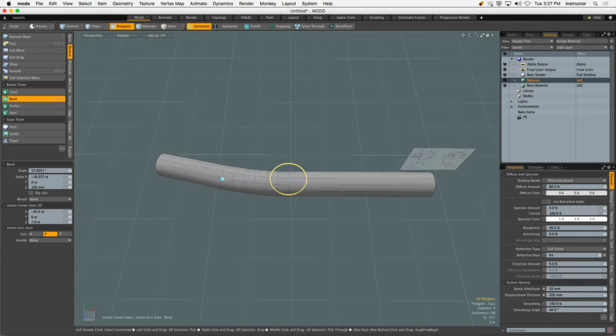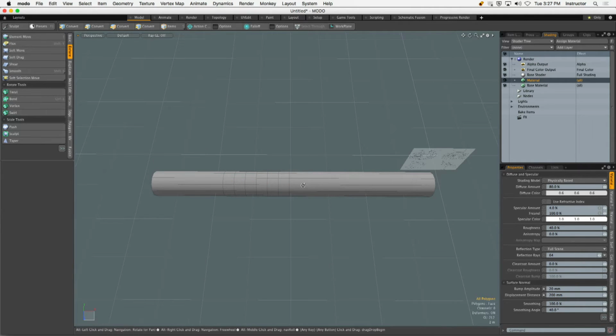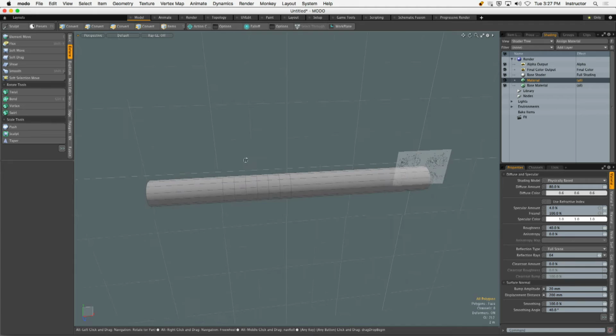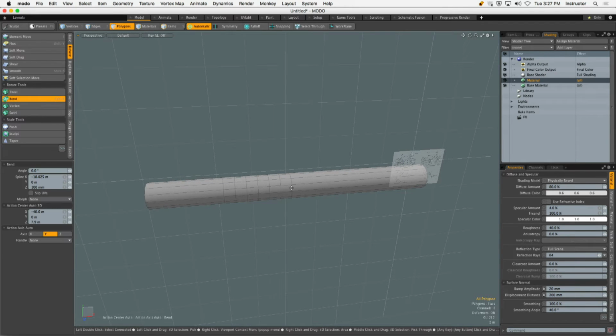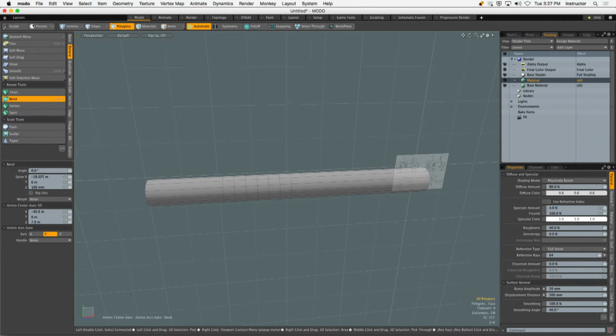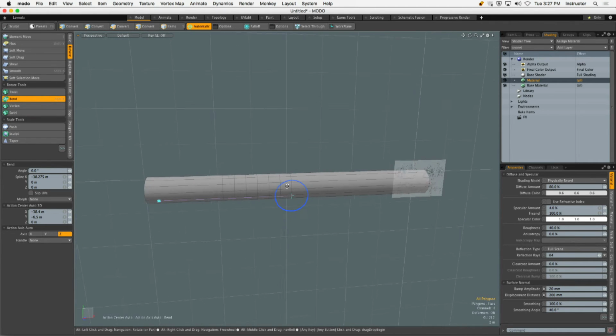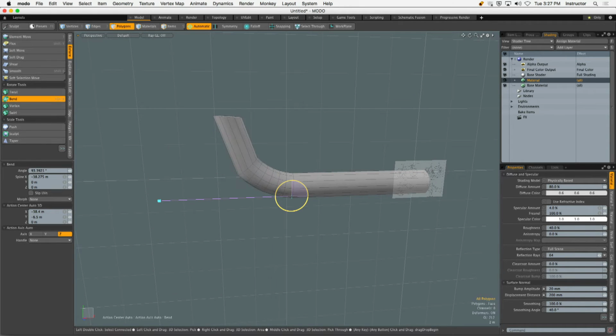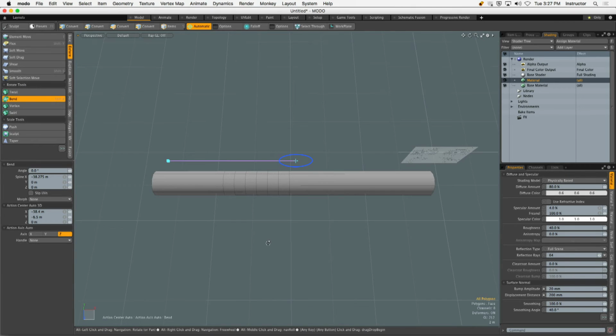So if I grab the little circle, you can see which direction and how we're bending it, right? If I drop the tool, change my work plane, or change my view so my work plane changes its orientation. Now, with the work plane cruising along the XY axis, the bend tool's axis plane is going to be flipped 90 degrees. And now I'm bending it like that, okay? So the orientation of that disc is really important.